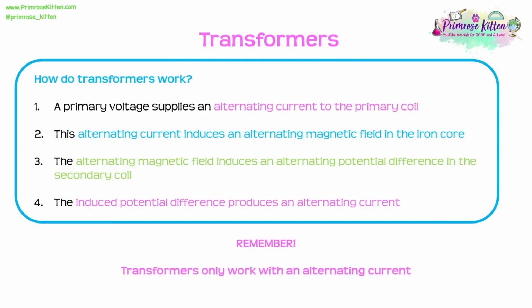As a final little reminder here and a top tip, don't forget that transformers will only work with an alternating current. If we connected them to a direct current like a battery, they would not work. We need that alternating current of a mains supply.